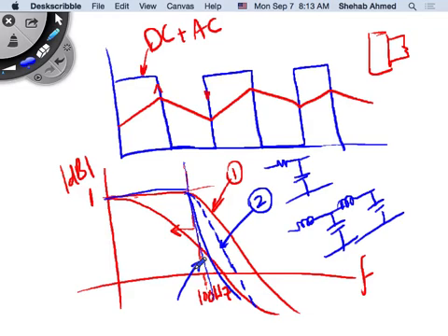If you have a simple RC circuit, for example, or a simple RL circuit, you're limited by tau, by the time constant of the circuit. If you apply a voltage across an RL circuit, there's a time constant that you're limited by, right? You cannot change that. It's L over R, right? There's a certain time constant. RC circuit, same thing, simple time constant.